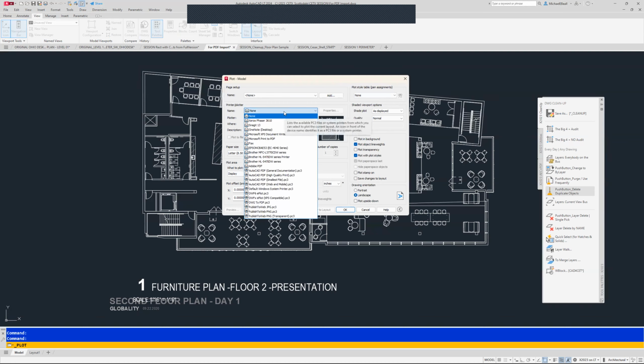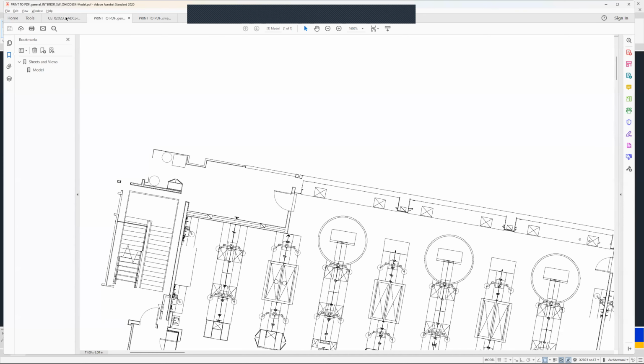So you've always had DWG to PDF. Most of you have Adobe PDF, but unbeknownst to many, about 4 versions ago, around AutoCAD 2020, they came up with this: AutoCAD PDF general documentation, which is what I just showed you, the one with the clear circles, high quality. And the smallest file option, so literally they are the smaller files.